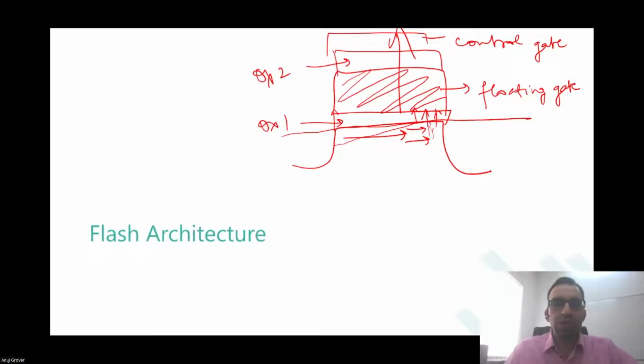So in terms of security, when we were talking about EPROM and EEPROM, when it is a one-time fused programmable memory, then you can delayer and find out where the fuses are blown off, so you can actually find out. But if it is electrically erasable and programmable, then you can't. So flash being an EEPROM is in those terms more secure. Is that okay?